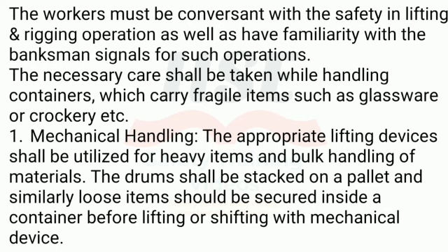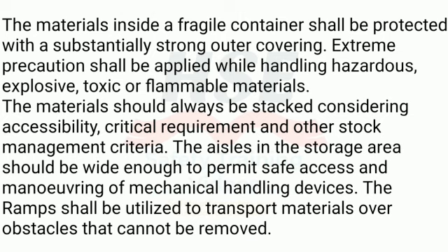1. Mechanical handling. The appropriate lifting devices shall be utilized for heavy items and bulk handling of materials. The drums shall be stacked on a pallet and similarly loose items should be secured inside a container before lifting or shifting with mechanical device. The materials inside a fragile container shall be protected with a substantially strong outer covering. Extreme precaution shall be applied while handling hazardous, explosive, toxic or flammable materials.